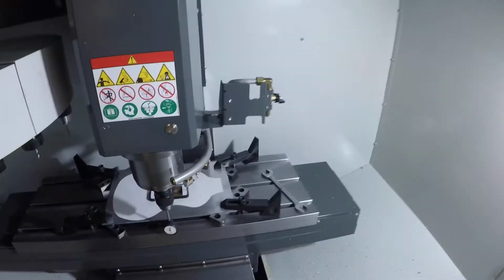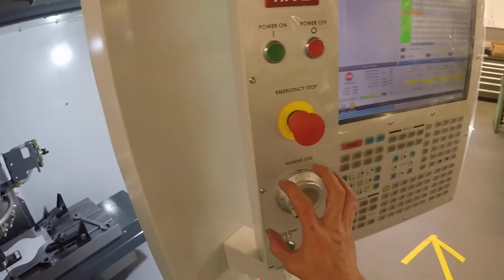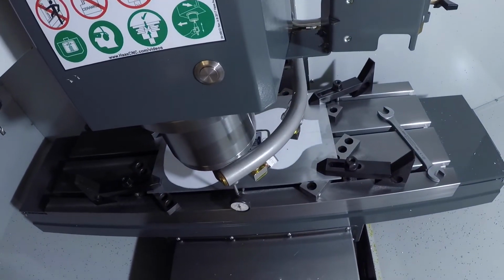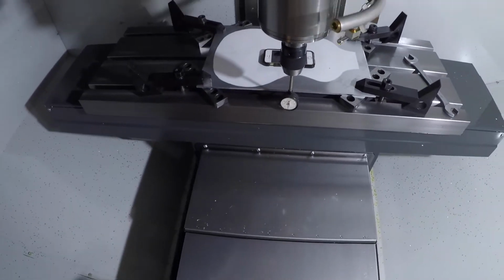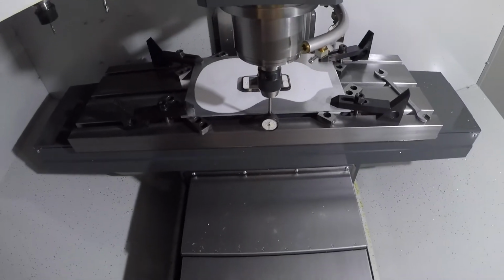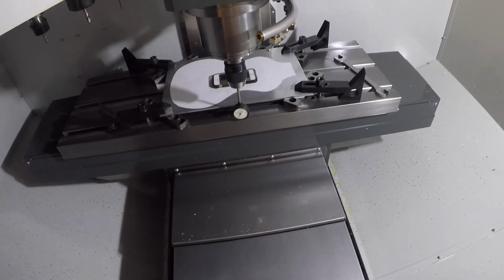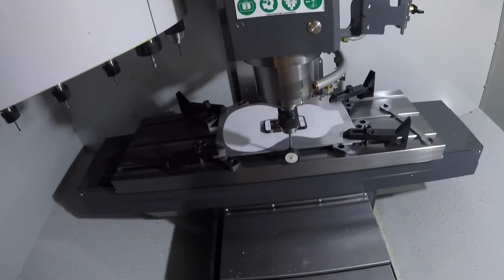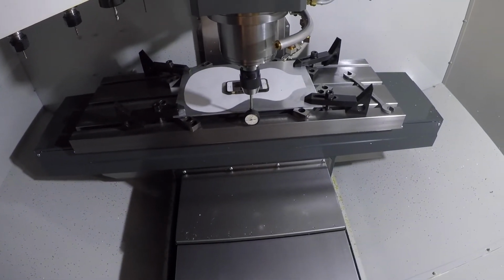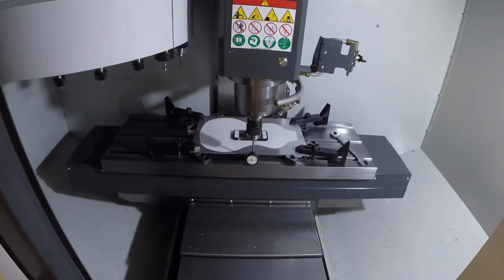Now I'm going to put the traverse wheel into thousandths increments. So now it's moving thousandths of an inch. And so we can watch in a moment that indicator will start to read for us. There it goes. For every tick on the hand wheel, I'm moving the table 1/1000th of an inch. I don't need to put it on 0. I want to see how straight this is.